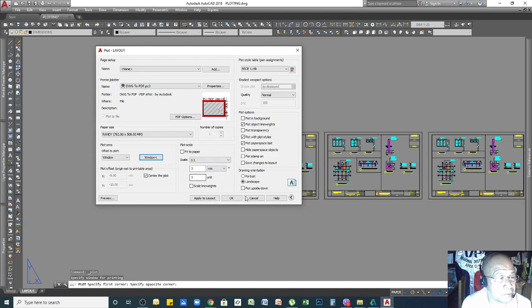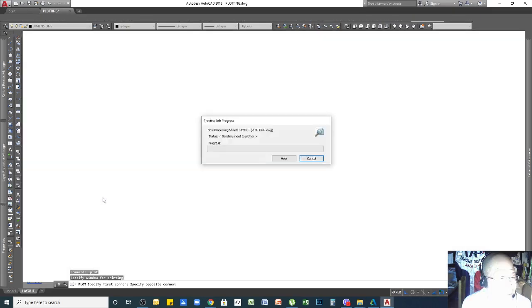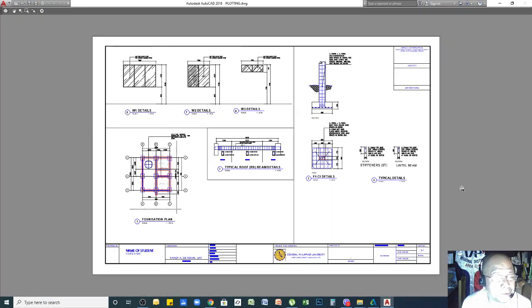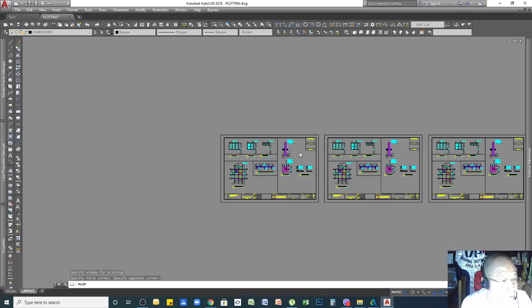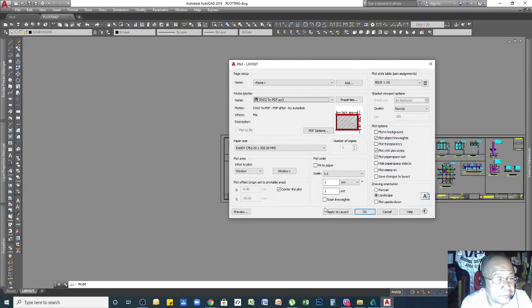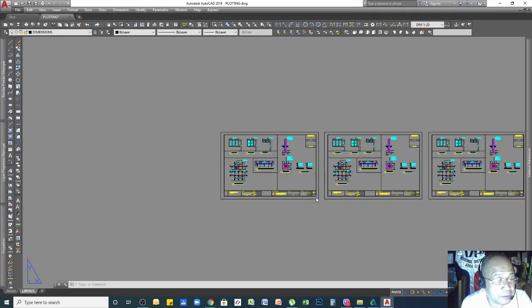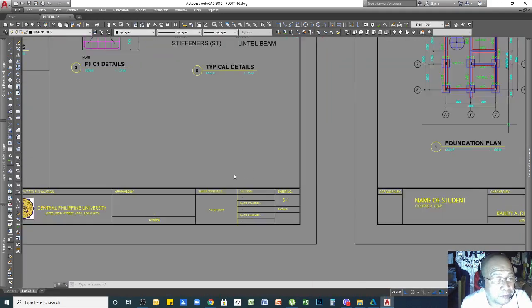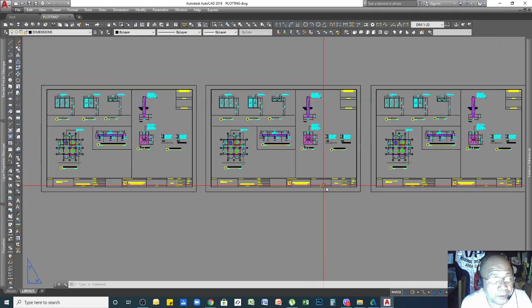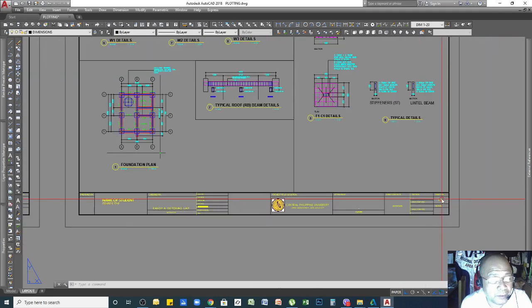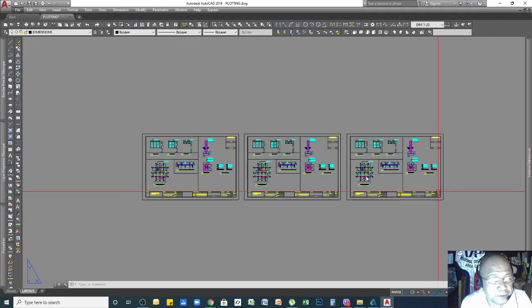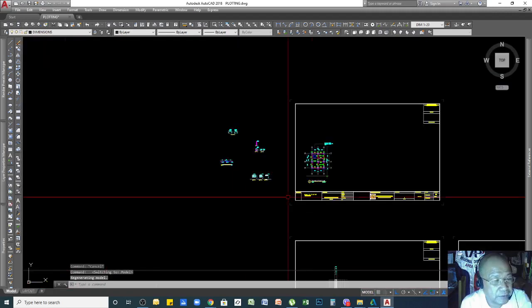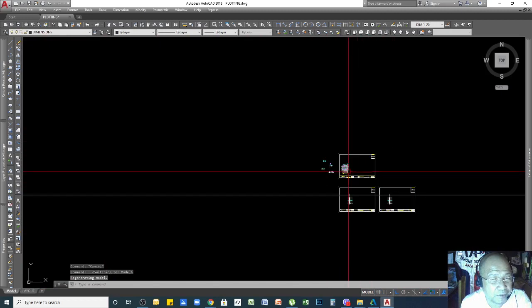And then before you go to OK, you check preview first. Check if the content of your drawing that you are going to print is correct or not. So as you can see here, it's S1. I think the drawing sheet that we use are all the same. Let me check why it is S1. Okay, because our title block is the same. I changed this one. This changes everything, I'm sorry for that, because we have only one drawing sheet here.